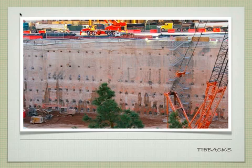So let's say we start, and recognize this is a gigantic excavation. We put our slurry wall down, we dig this whole thing and we put our slurry wall in. After that slurry wall is there, we start excavating from the top. And as we excavate, when we get to about here, we put this row of tiebacks in. Then we keep excavating and get to about here, then we put the next row of tiebacks in. Then we excavate more, we put the next row in. So it works its way down, so you're always adding that reinforcing as you go down.